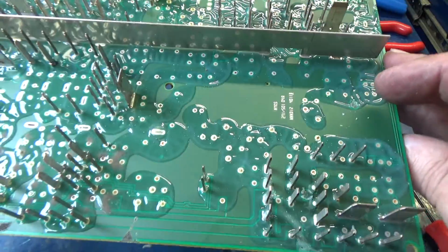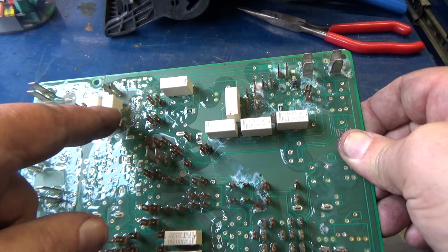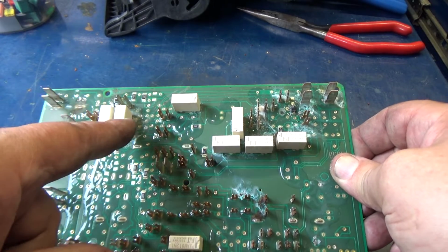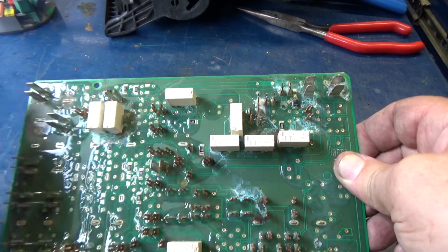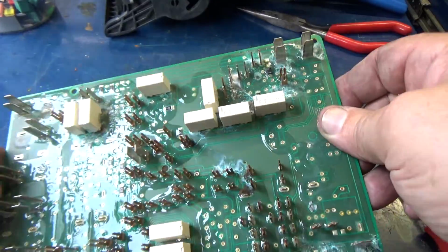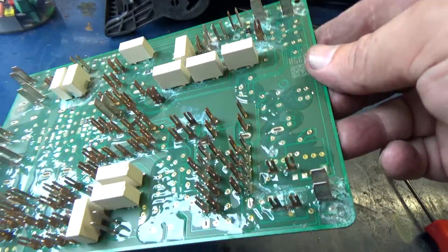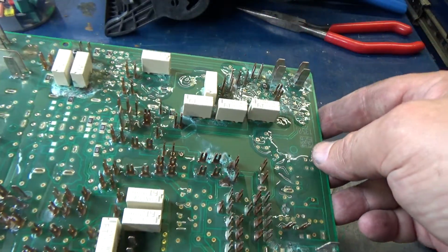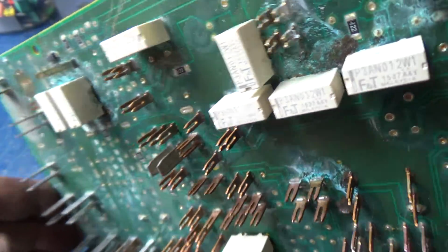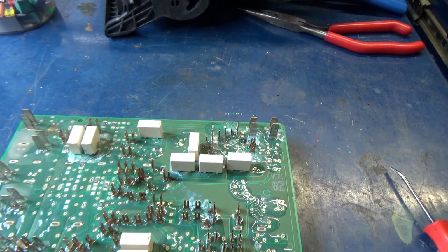But what I'm going to attempt to do, mainly for this video, is I'm going to verify that this is the actual relay we need to go after. If it is, I'm going to see if I can unsolder it and solder that new one in, and then clean up this corrosion with some contact cleaner. We're going to put this back in and see if we have any luck with it. If not, I'm going to be ordering another one. The Denali one was perfect. Other than that bad relay, there was no corrosion on it or anything.